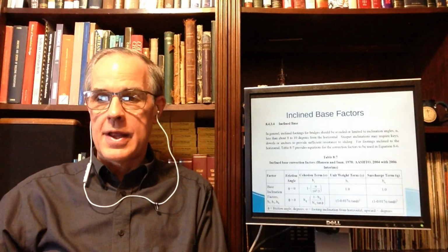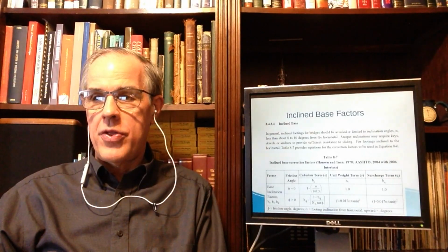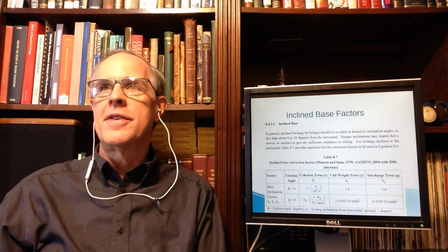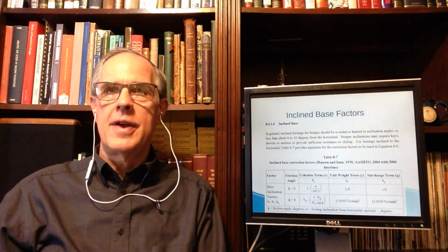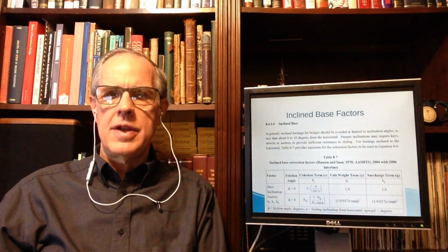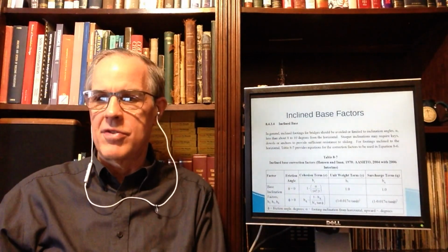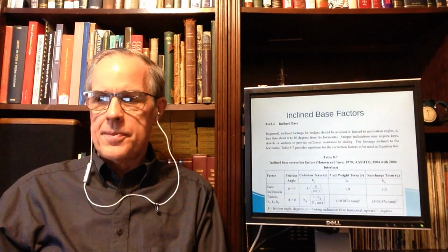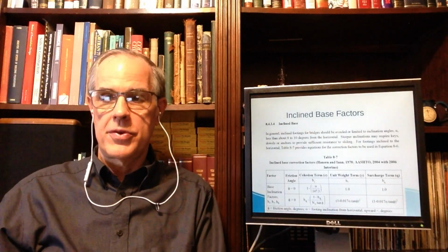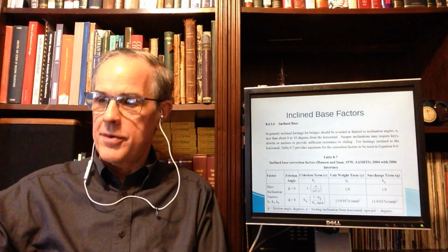The second, inclined base factors. Same division. That's important if you've got a slope in the base. Now, sloping bases you'll see sometimes. They're primarily used either depending on the stratigraphy or to create some potential for lateral loading conditions. For this course, I'm not going to be bothering you with inclined bases. So we'll just call it that. But the factors are applied in very much the same way as the shape factors.